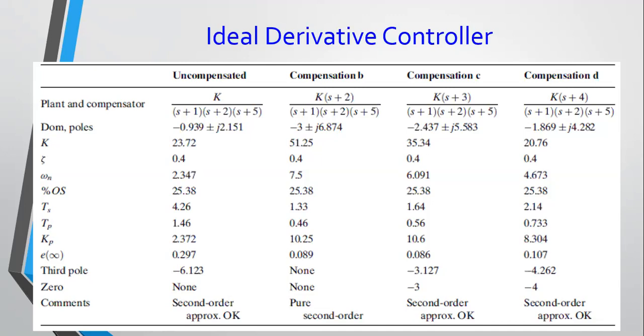It can also increase. So it's very important for you to cross-check your steady state error as you're doing your transient changes. Remember, when you were doing your PI controller or lag compensator design, even there we had slight changes in transient. Even if we were not tackling transient, you wanted to maintain it, but you had slight changes, and you have to cross-check if the changes in the transient are acceptable or not. Similarly here, as you're doing your control design to deal with the transient of a system, the steady state error would also change. So you have to cross-check, is it acceptable? In this case, your steady state error is reducing, so you won't have a lot of issue. But if it were increasing, you would need to make adjustments.